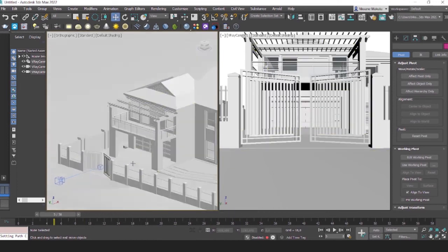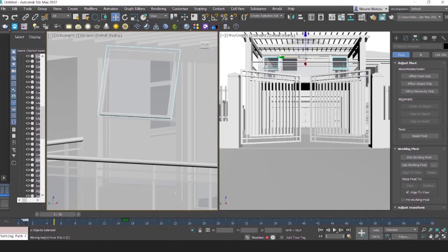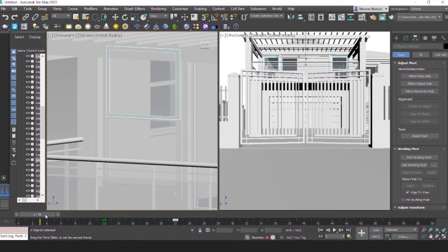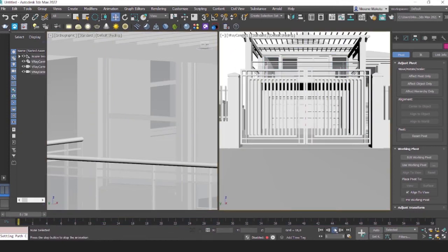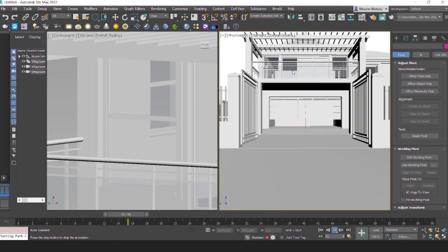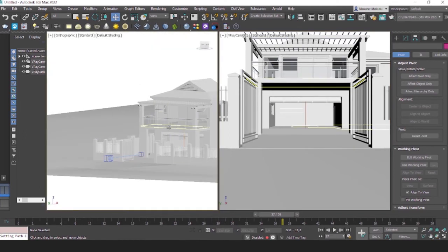What you do is select the window glass and the frame. Once you select them, those green markings come. So you can just drag it to wherever you want it to start and wherever you want it to finish, right? Now once you play your scene, they are closed and now they start to open. So that's how you start playing with those settings.